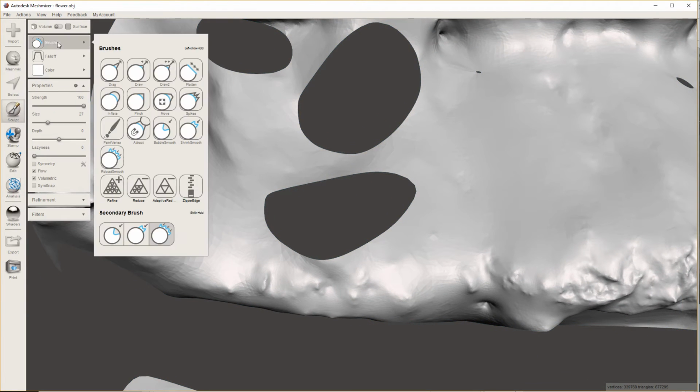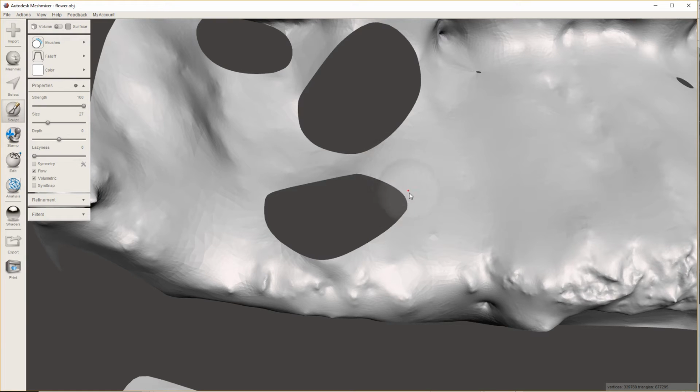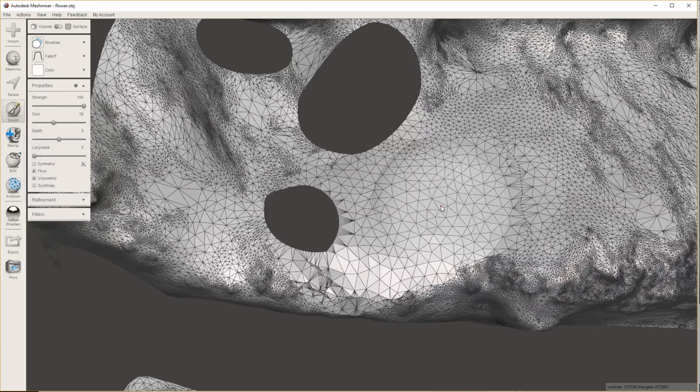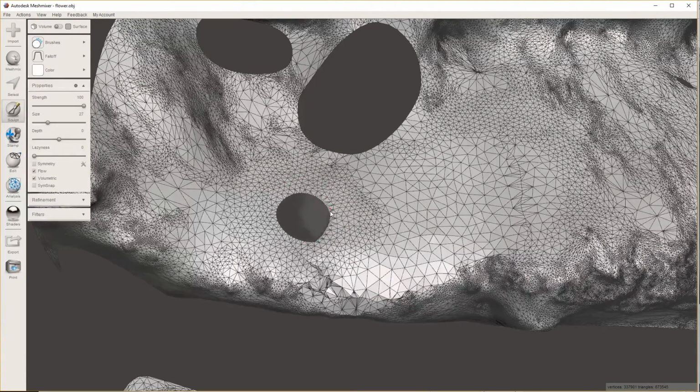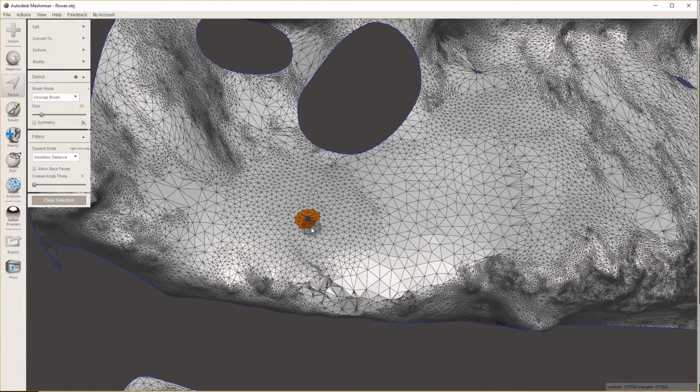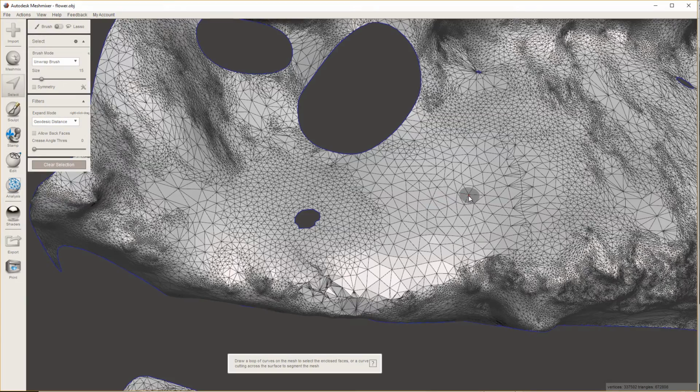So you can go in and use the Robust Smooth tool to do this really awesome kind of hole fixing. Remember, the larger you make the tool, the more your mesh gets kind of loose like this, so you can kind of keep it a little bit small and move it in a little bit bigger like this, and make it smaller, and now it's a really good candidate for just going in maybe with the select tool like this, and then just deleting a little tiny bit and then doing a hole filler. So that's a really good thing.